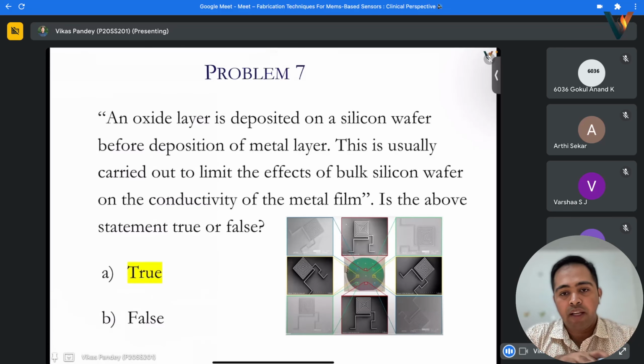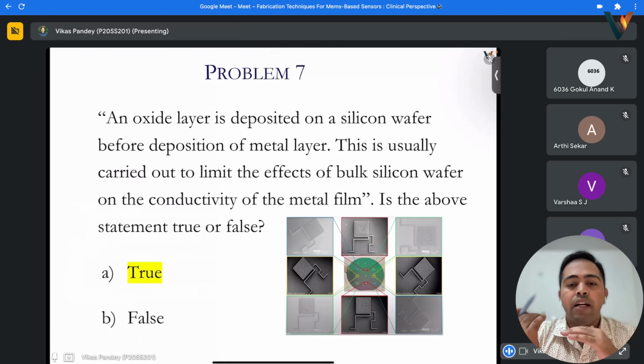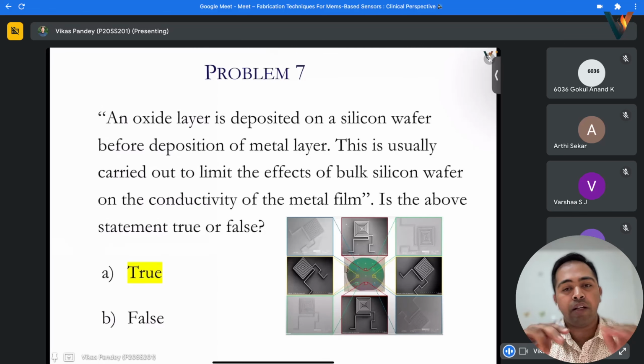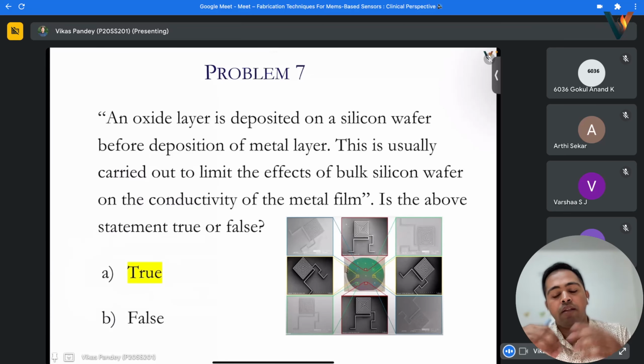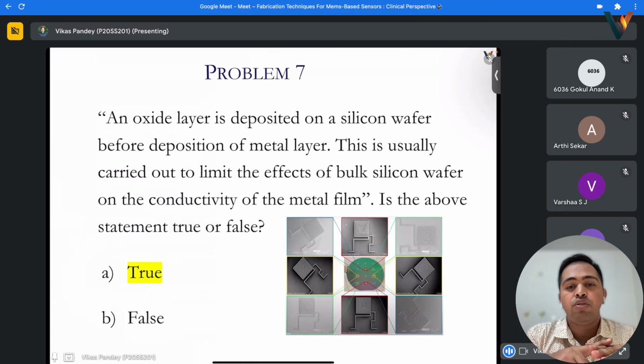Above it, again, our desired heater is made. After that, we again need to isolate it, so again 200 300 nanometers of some isolation is put, and then again the electrodes are put. This is the process, and it is used to isolate one layer from another. In the case of biosensors, we go for maybe 4 5 layers maximum.